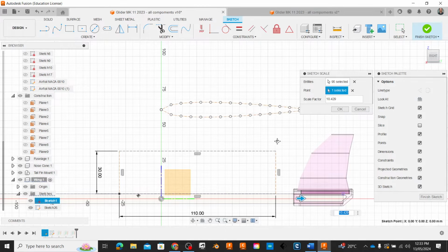All right, now the last profile that we do will be a wing tip. And we're actually nearly there, which is really good. So right-click, edit sketch. So I'm going to go to modify, move copy, rotate, minus 3.5 degrees.